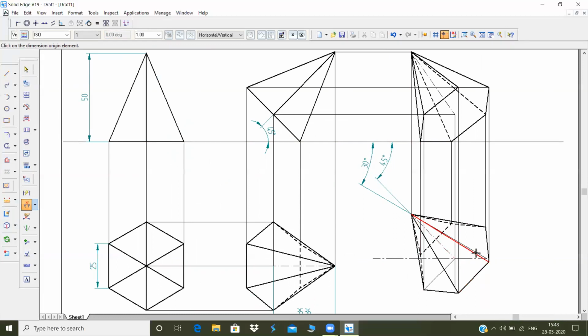You can draw it by the same procedure you use for planes in a beta angle problem. Only thing is, instead of the diagonal etc., here you have your axis. After you get 2 points, it is very easy. So you are getting 2 points as O1 and O, and you can very easily get O1 and O because you will get those 2 points till here. After that, you find all the other points using O1 and O. Let us say this is A, B, C, D, E, F. All these you can find just with O and O1 as reference. With this as a reference, you have to measure from here and redraw this. This particular position you will get very easily.